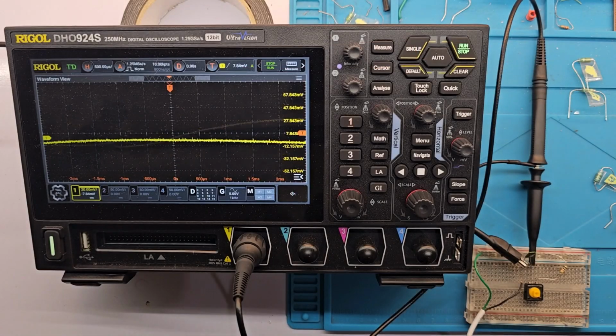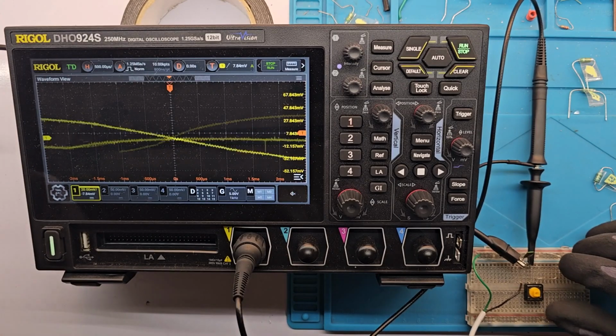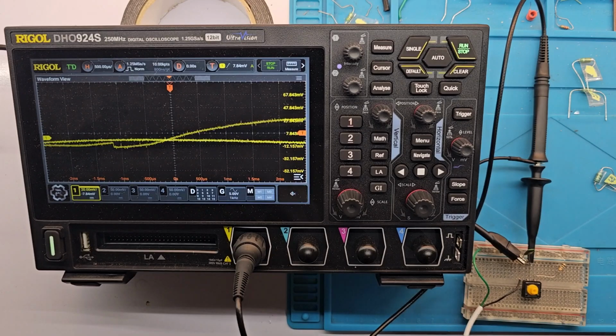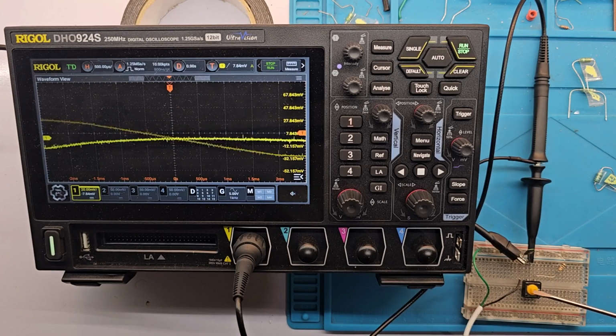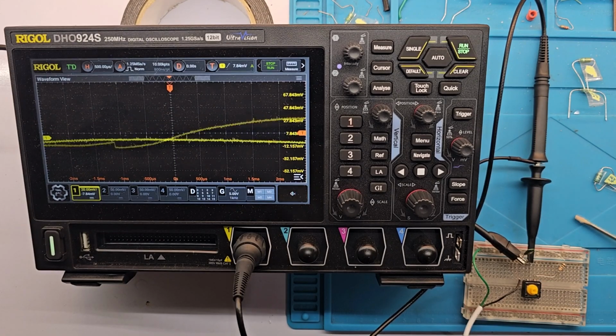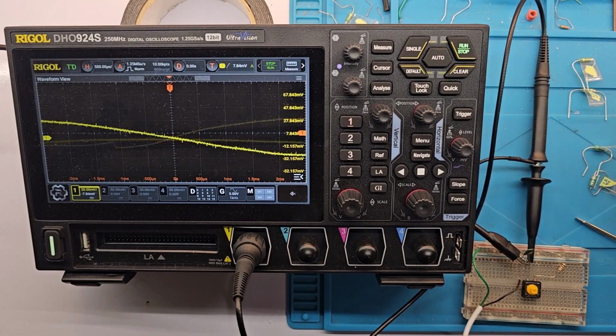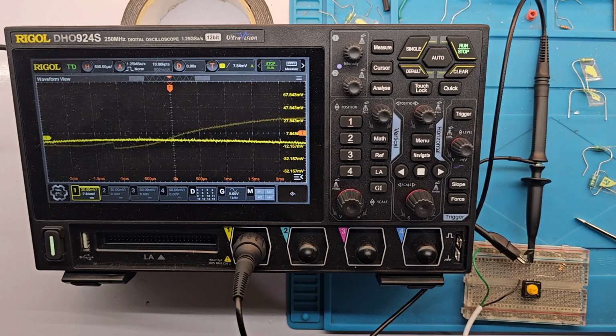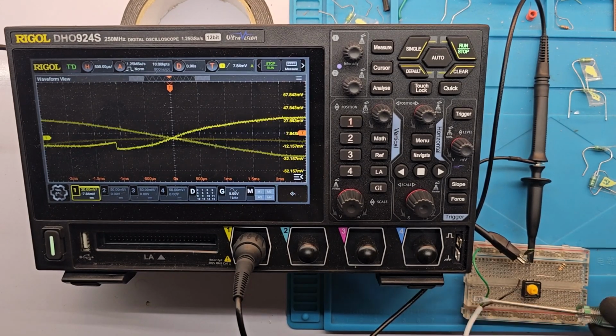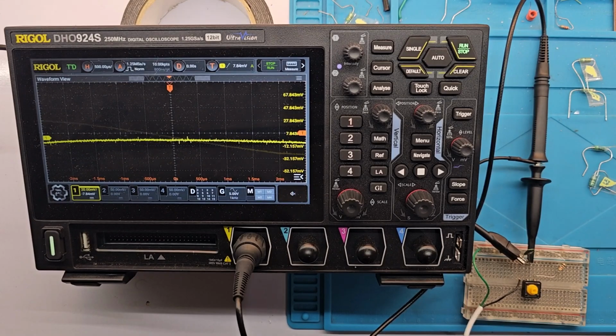And now let's follow the procedure. So this specific circuit on the breadboard is very much what I just showed you on the screen. I have my oscilloscope probes connected to the 1 nanofarad capacitor, and I have a 1 kilo ohm resistor. This is a push button, and I have to put the inductor in it. And this is the power supply, these green and red lines. This is a 4 volt DC power supply.